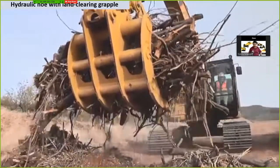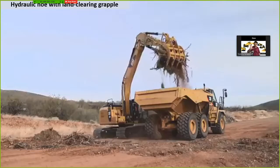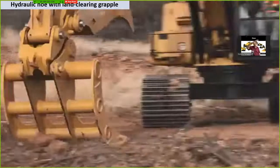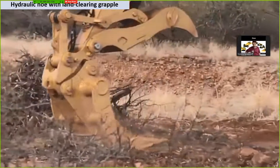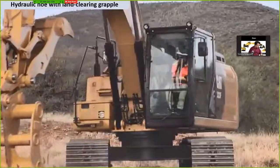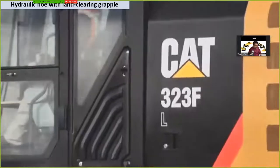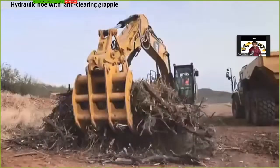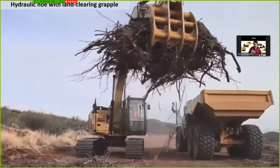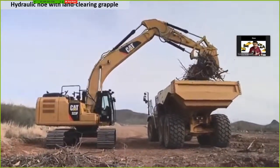And maximum dumping height, it means to what height your bucket should go up and it can dump the load. That could impact the choice of the hoe. And of course, the hoisting capability, it means handling pipes and trench boxes. All of these factors could show you which hoe you would select.